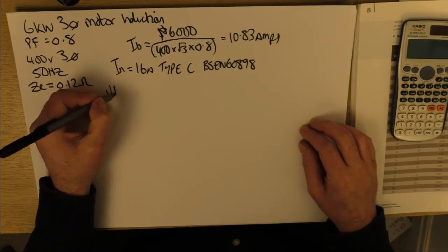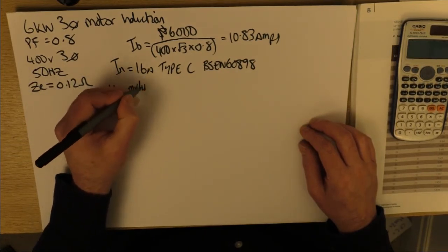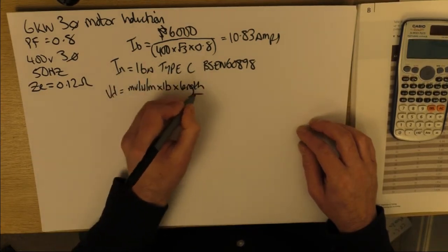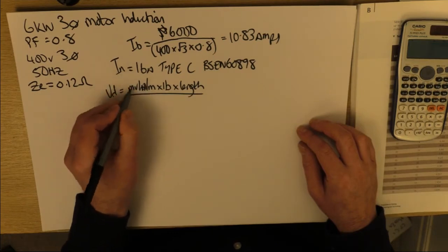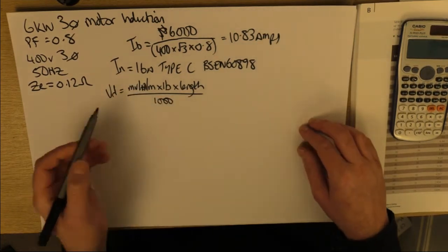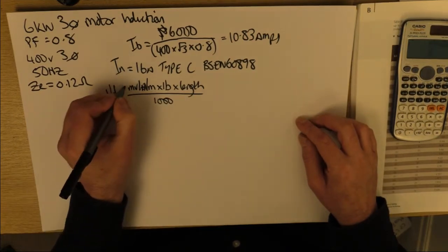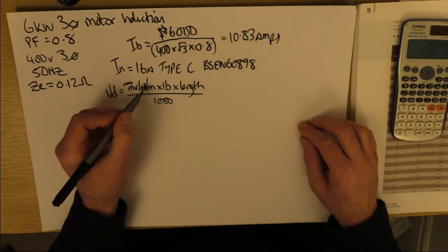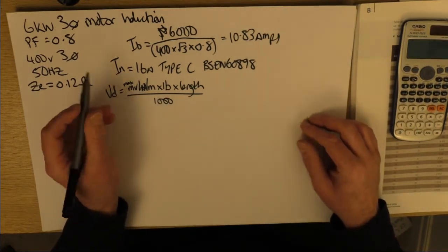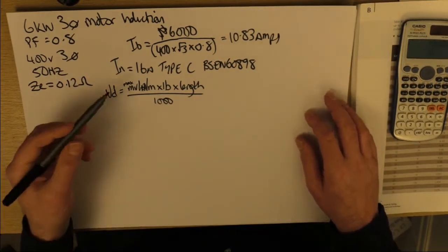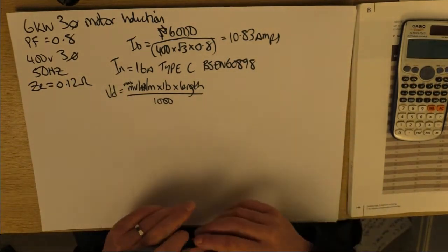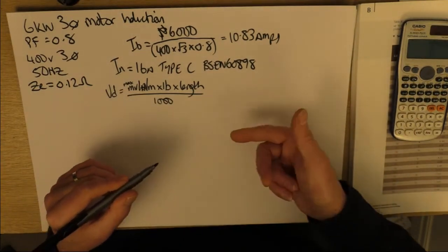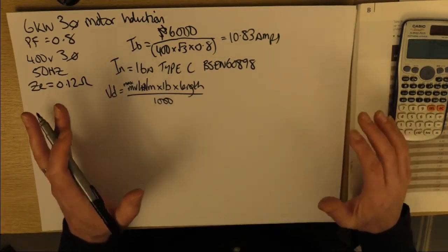We're going to check out that volt drop equation first. We're just going to flip it on its head, transpose for this, and what that gives us is a maximum millivolt per amp per meter value, and then we go straight to that table and choose a cable based on that. Sometimes you get it right, sometimes it doesn't work. We still need to check it for current carrying capacity, which obviously we'll do next. So it's just the other way around really, but we're still checking for the same stuff.